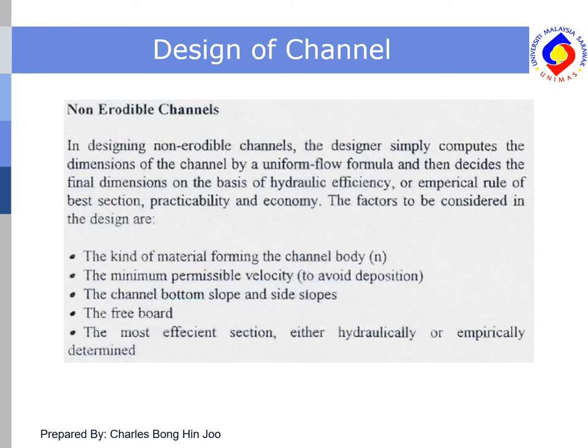when it comes to this design. For example, the kind of material for the channel body, the minimum permissible velocity, this is to avoid deposition of sediment, the channel bottom slope and side slope, the freeboard, and the most efficient section, either hydraulically or empirically determined.